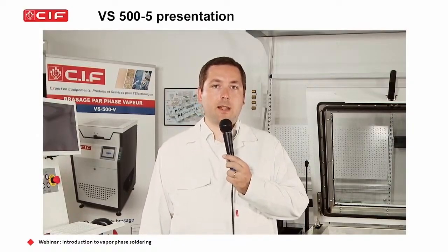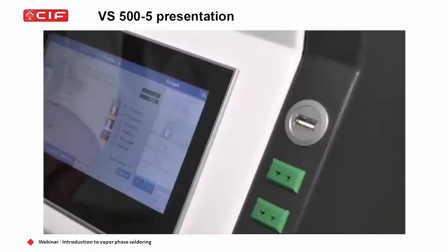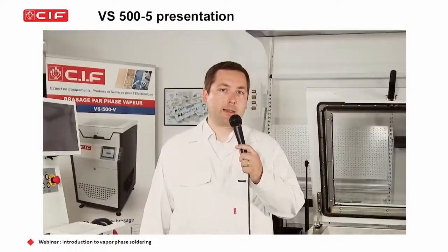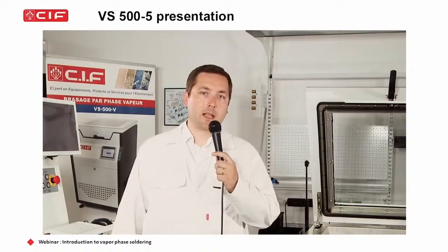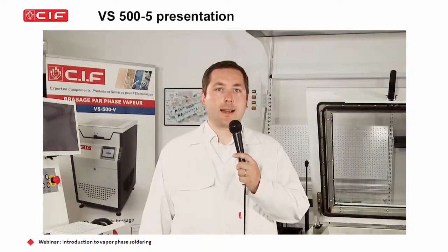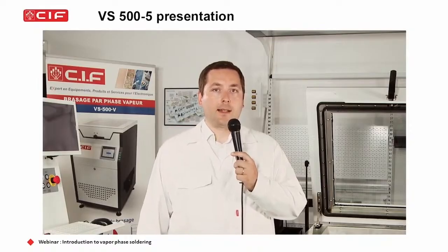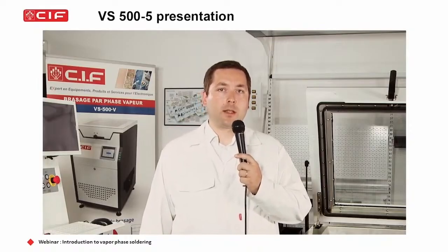For the data themselves, you can here plug a USB stick and recover the production data from the PLC, including Galden temperature and the real temperature at the side of the PCB, because we have a thermocouple here mounted on the lift.